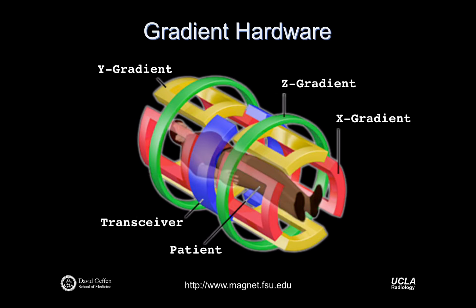Yep, so this is the transmitter for the B1 pulses or RF pulses. And as it can transmit in the radio frequency range, you can turn it off in the transmit mode and switch it to be a receive mode antenna. And so as a coil, it can actually receive the MR signal as well. Turns out it's not a great receiver because it's not that close to the body, right? It doesn't have great receive characteristics, and it's designed really to be a transmitter.